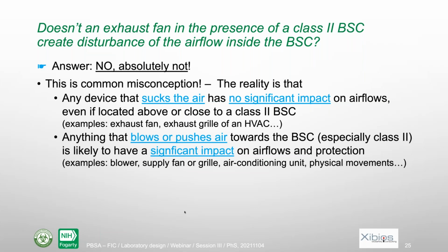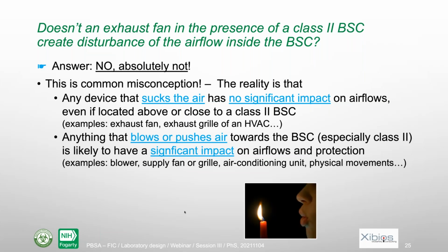On the other hand, if it's a device that pushes the air towards the biosafety cabinet, in that case, it's likely to have a significant impact. So if you take the air away from the cabinet, no impact. If you push the air towards the cabinet, you will have an impact. This is very clear, and a good way to remember that is to think about a candle.